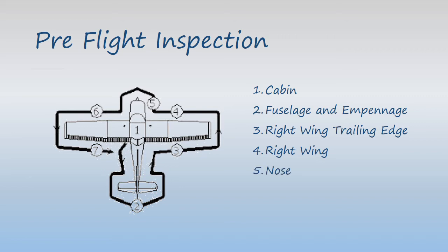At first we check the engine oil quantity. And then drain some fuel to check for water accumulation in the fuel system. Then we do an inspection of the nose wheel and the strut. Then you can visually check your propeller condition, alternator belt condition, and the landing lights. Then you have to check your static port for any blockage, and then the left wing fuel quantity check.